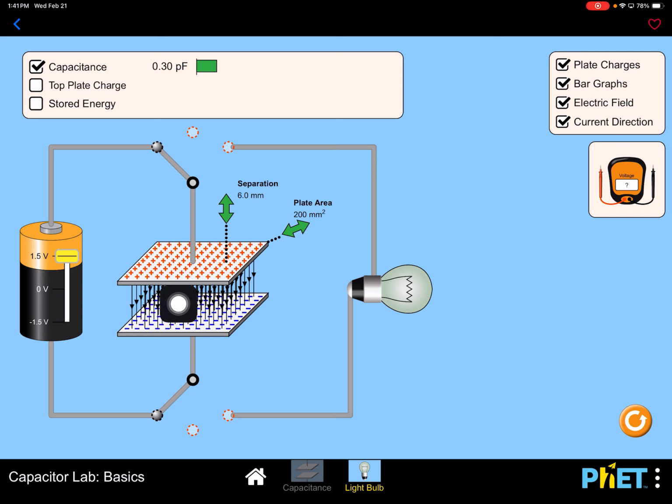The limiting factor is you can make this electric field only so strong. If it's air-filled, what is the maximum the electric field can go? 3 million volts per meter. And if you charge it any greater than that, it'll discharge through lightning. All the energy stored will just go away, poof. So it wouldn't explode? It won't explode. You'll just have sparks flying and things burn.